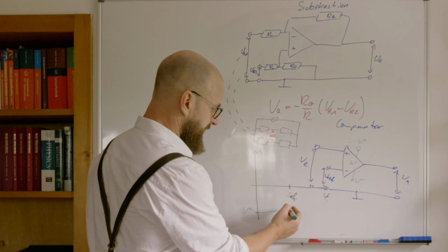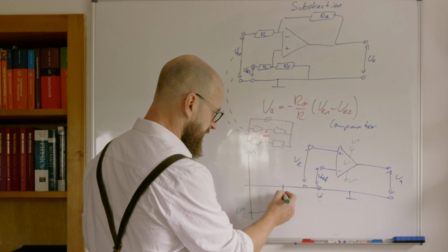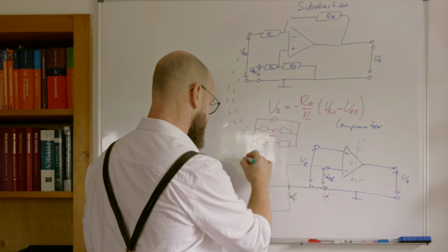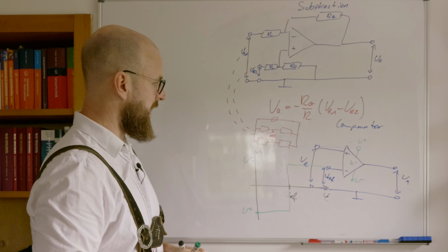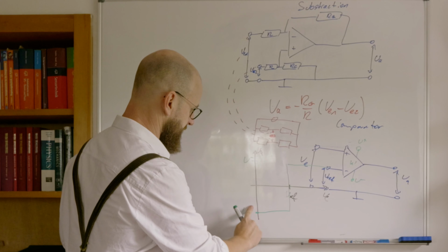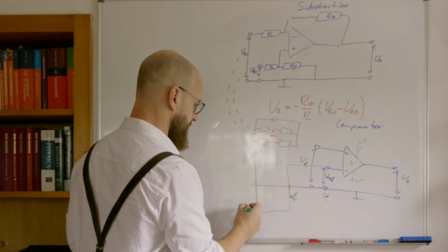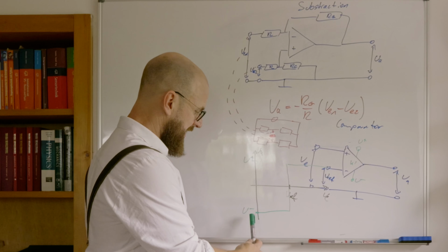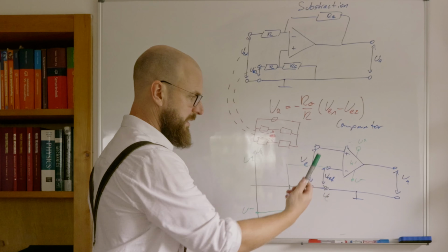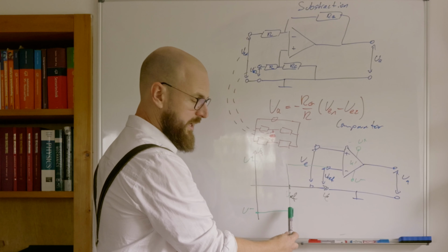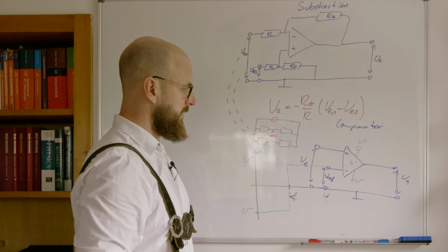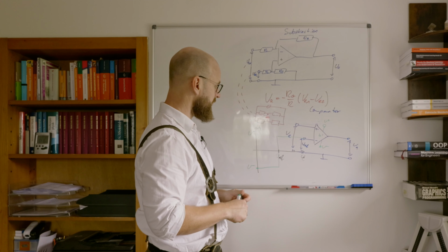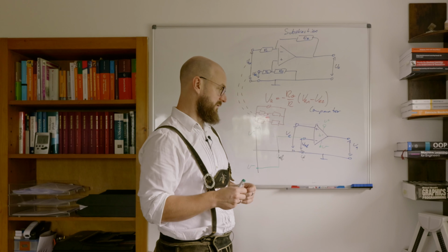So it's U+. Then coming near to that reference, we very abruptly switch to the other side over here, to the other voltage. Let's exchange the plus and minus. That doesn't matter at all, but just to see what happens, it means we get the maximum output voltage we can have. As long as we are smaller than the reference voltage, we get the maximum output voltage on the other range, as long as we are bigger than the reference voltage.